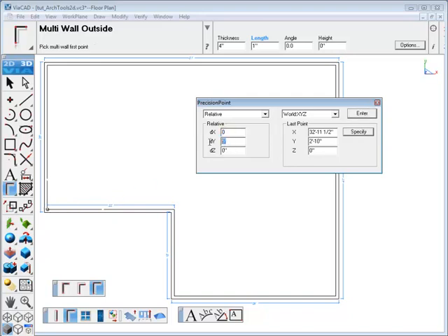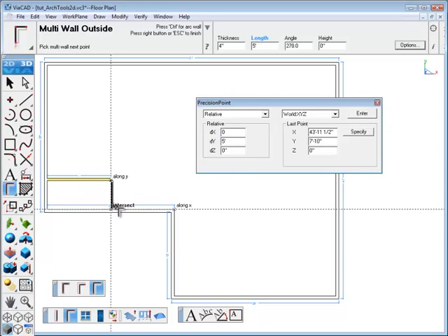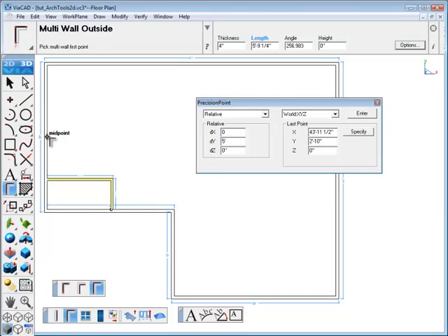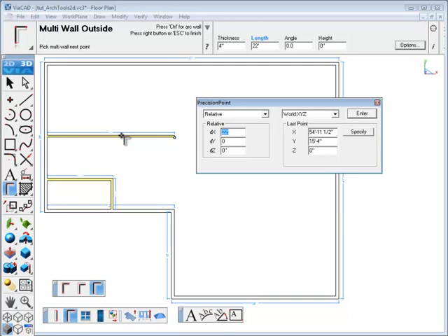So we'll click to set the point. Now enter the dy value of 5 feet, and that sets the start point 5 feet up from there. And then we'll use the logic cursor to place the other 2 points for our room. Click the midpoint. We'll drag out and set dx at 22 feet and dy at 0, and that sets a 22-foot wall. And then we'll just go up and set the other wall.